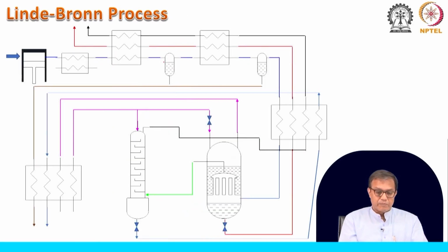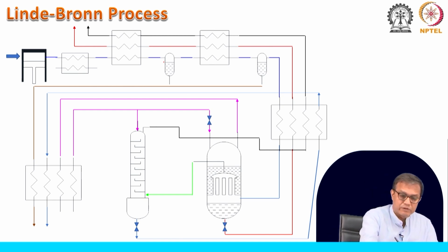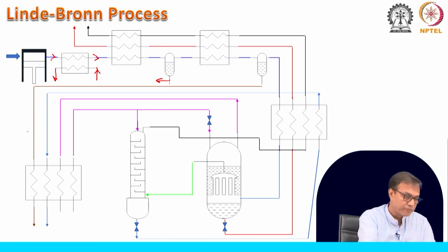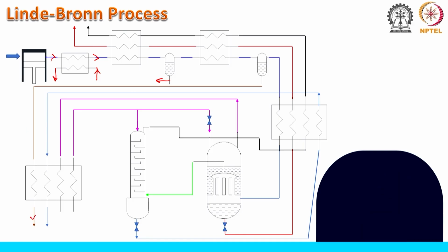This complete process which I have drawn with the lines, you can have a look into it. Here we had the precoolant ammonia, and it was this coke oven gas which was coming here. It was cooled initially with the ammonia, then there are two 3 stream exchangers. Here some amount of propylene was extracted, then we have the ethylene that has come out from here.